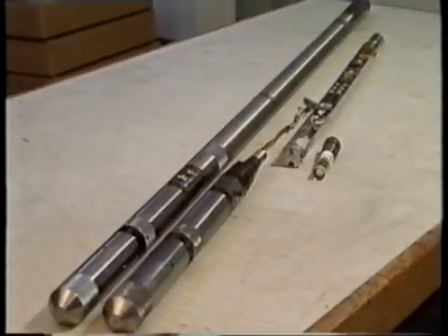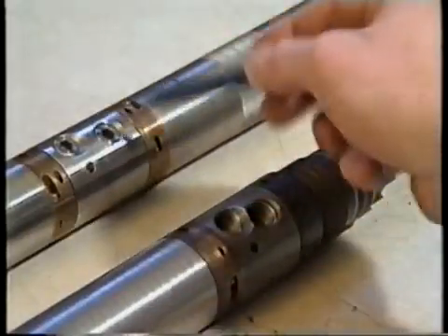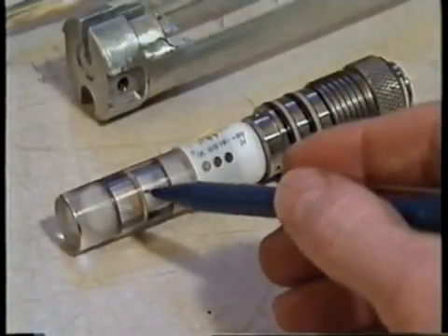It's not uncommon to run other tools for additional pressure analysis, like this production pressure tool, or PPT, with side port entries and quartz pressure transducer. We understand then that in order to measure the downhole rate, we must know something about the relative volumes of phases flowing at downhole conditions. We can gather that information with a gradiometer survey run on our flow meter. But what does our flow meter measure?